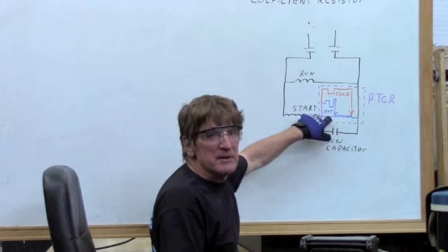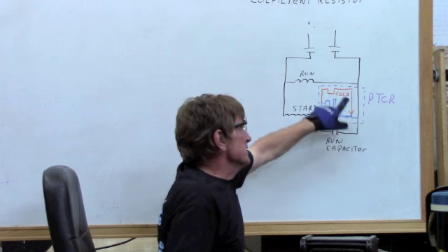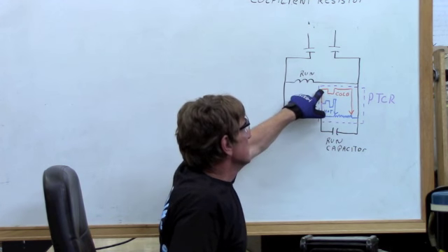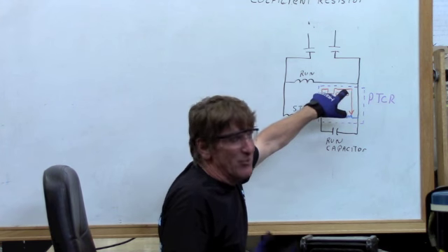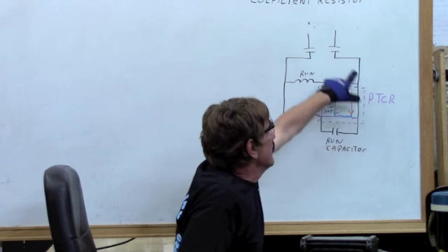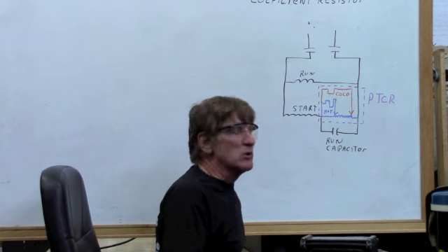Otherwise, the resistance is going to be too high and that compressor will not start. So if it's cooled down, resistance is going to go from the start winding through, equivalent to that wiper, down to that lowest resistance point, and back to give me my power to actually get this motor running.